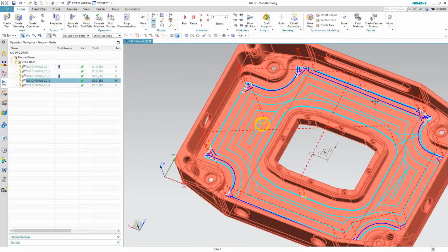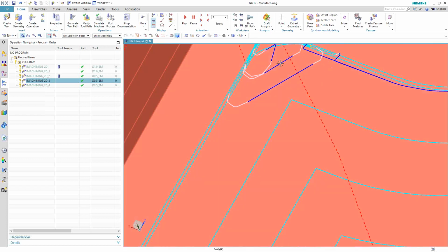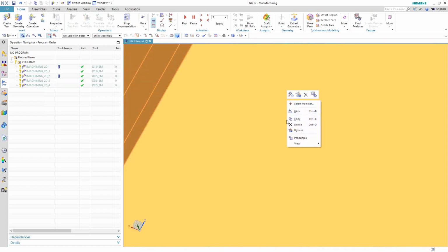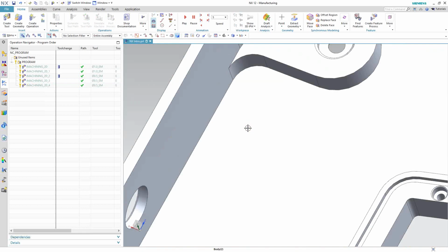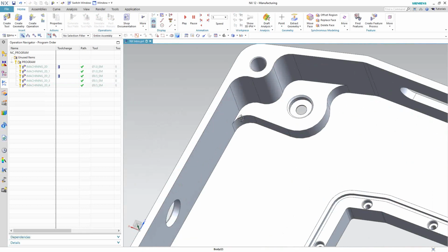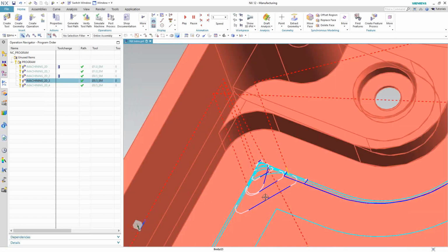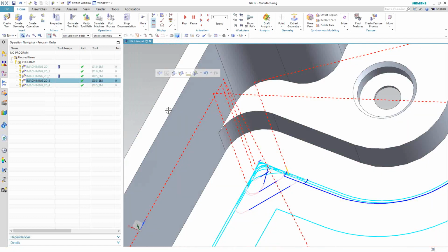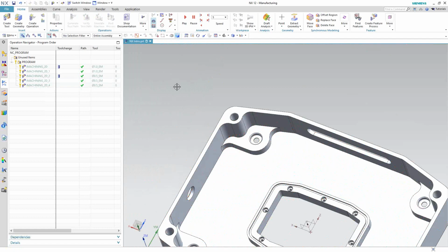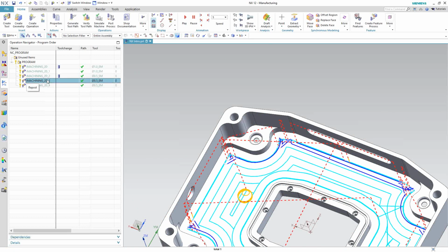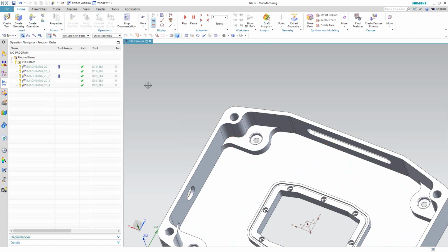So you have that contour style toolpath. You can see that it's pretty much offset. If we zoom in on the walls, we can see that there's still a little bit of iMachining action going on. Just zoom out. Turn that toolpath back on. There's still a little bit of iMachining going on in that corner. Again, because the previous toolpath left behind 10 thou of material, so there's probably some additional material in there that's a little more than 10 thou. So the iFinish went in there and pretty much did almost like an iRest operation to finish that. So now that floor is completely finished.